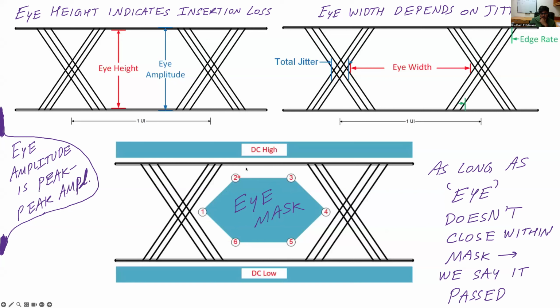We can say this because what the eye diagram actually does is it tells you where you can actually sample the signal. So if I was to sample the signal exactly midway here, I can distinguish the signal exactly when it is high and when it is low. Because I am both in amplitude, I can distinguish a high and a low. And also, I'm far away from where the transitions occur, so that there is some time till when the signal becomes unstable again, which is called the setup and hold time, which will be covered in the CMOS driver design part of these lectures.